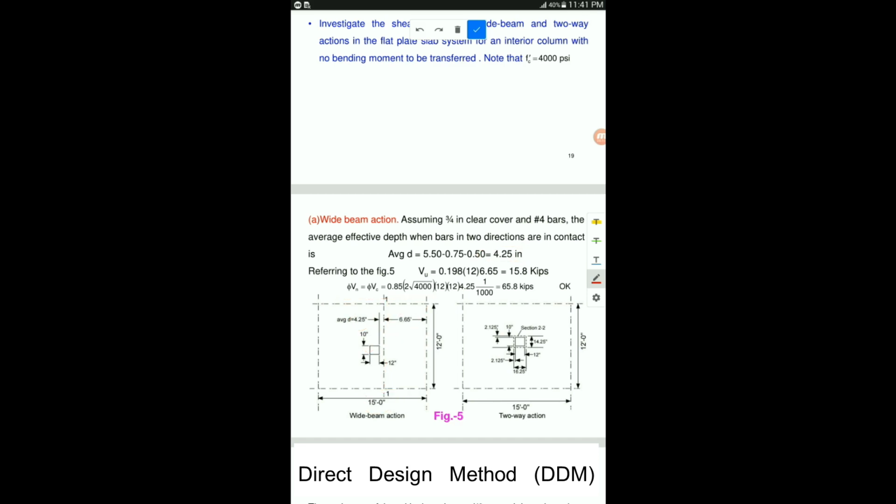In order to calculate the one-way shear this slab will be experiencing, you have to multiply the floor load or pressure load which you calculated in step 1, which was wu, the total factored load, of 198 psf. This has been divided by 1000 to convert into kip/foot squared. You multiply this factored load with this area here, which I'm highlighting right now.